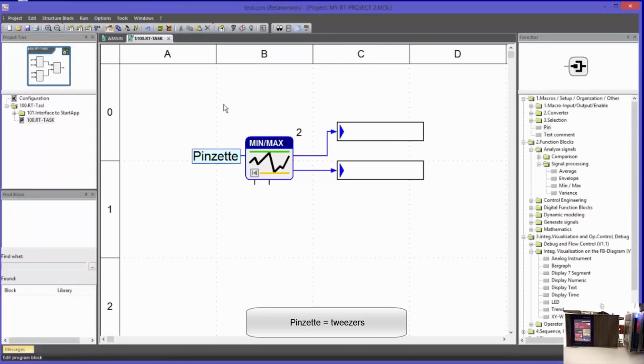Application connectors are implemented over special variables. These variables, on the other hand, are implemented over block attributes and the block diagram. In part 1 we have already connected the I/O variables to this min-max block over the block attribute. I could now connect the application connectors to this output of the min-max block. As you can see, a block has already been assigned here.